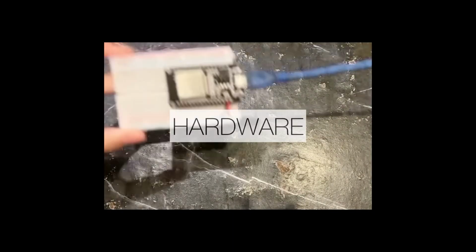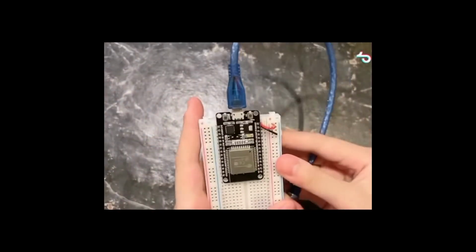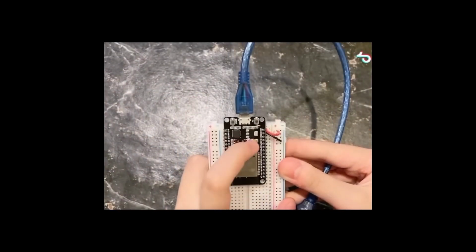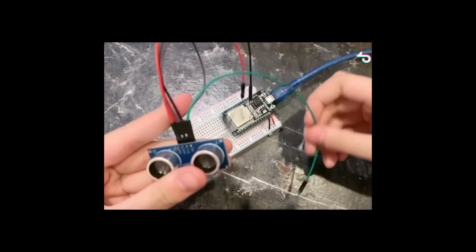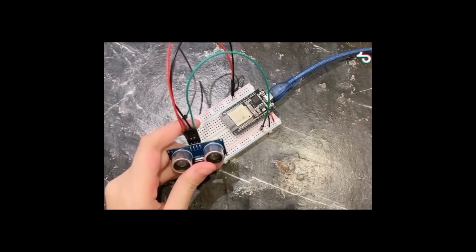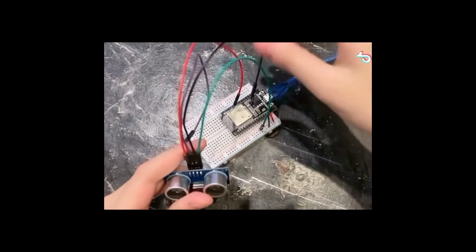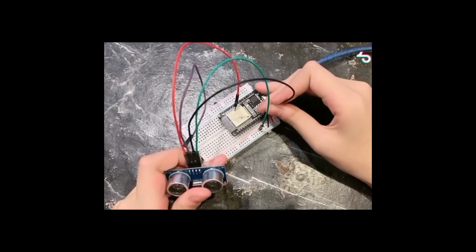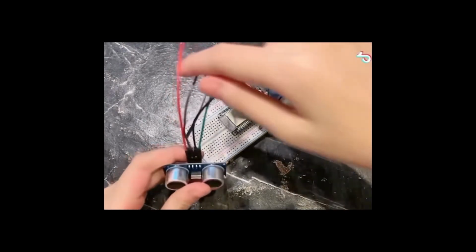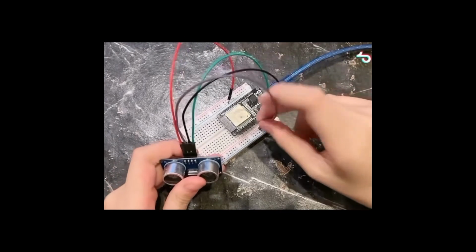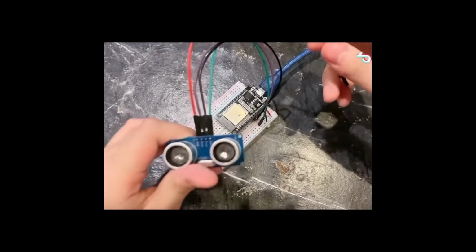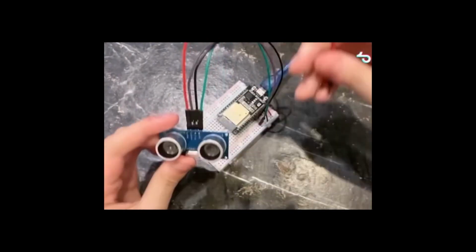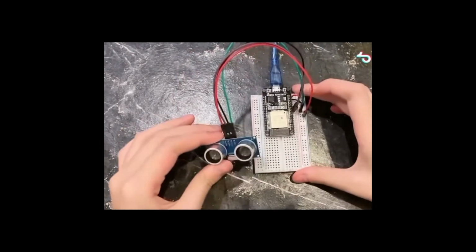For the hardware part, we use ESP32. We're gonna connect VIN to the positive and ground to the negative. Next is the ultrasonic sensor. We're gonna start with VCC to the positive. And next is trig. We're gonna connect it to D27. And the echo we're gonna connect with pin D26. And for the ground, we're gonna connect to the negative like this.